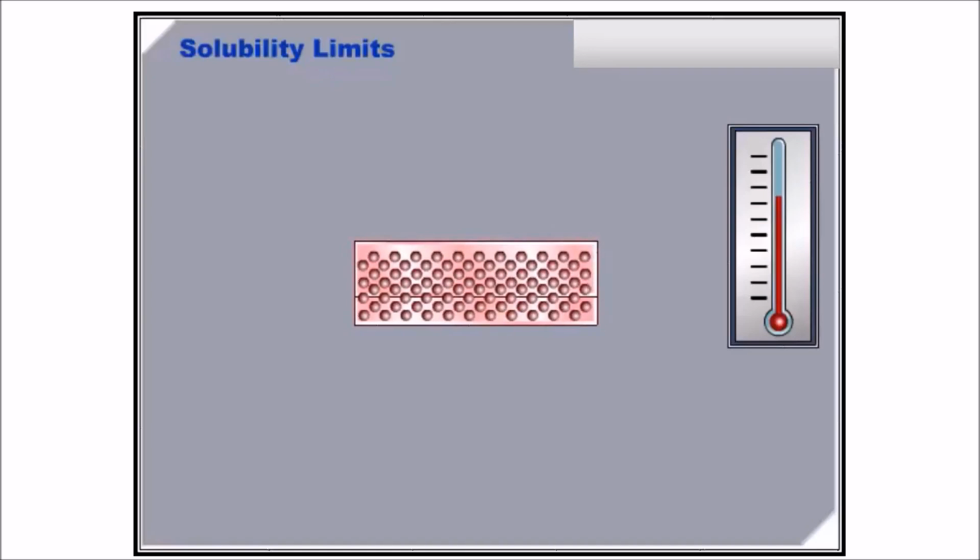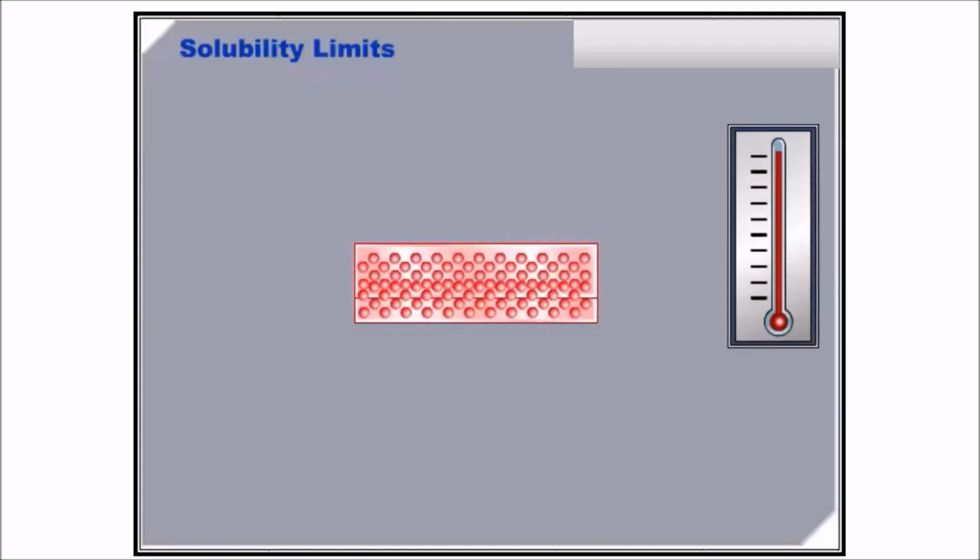The higher the temperature of a metal, the more dissolving of a second element will occur. Thus, we can get metals combining even when both are solid. Of course, as the metal temperatures are raised, the amount of diffusion and solubility increase.